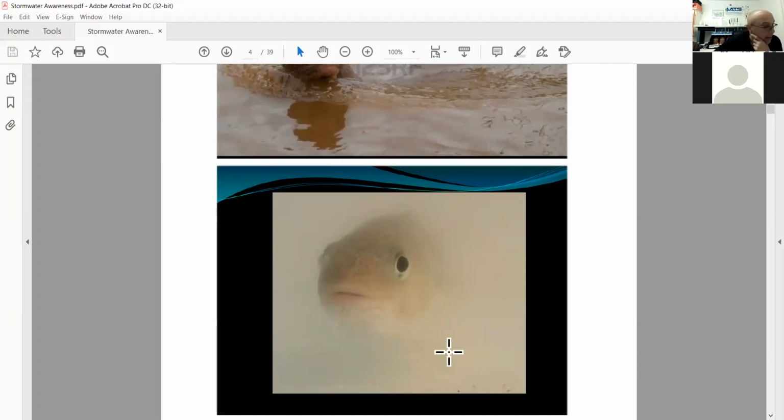And then the turbidity range for construction discharge. Right now, it's at 250 NTU max with just BMPs. The new permit coming out is stating a similar value. But when you're using an active treatment system, because they can produce very clean water, those turbidity values drop to a 10 NTU daily weighted flow average and 20 NTU maximum out of any single sample.